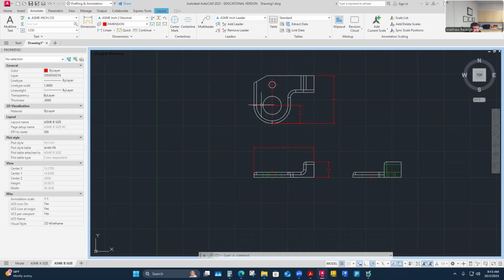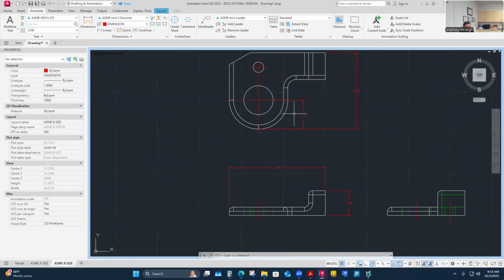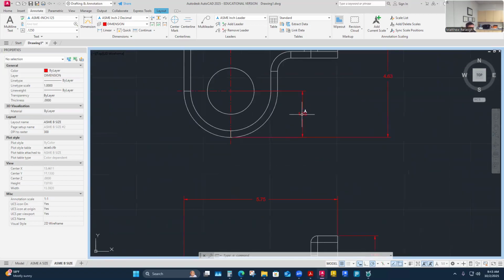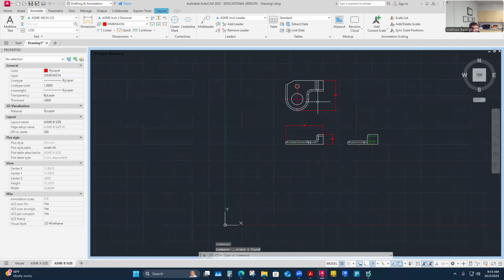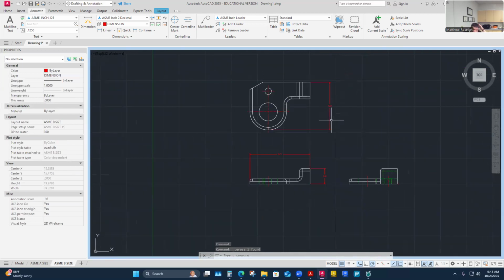Maybe you're establishing the center line of this out to here, but you've almost added a fourth pull point is what I'm talking about. And I think a good rule of thumb is try to stay as low as least amount of datums as you can to get the information across. And think about where the dimensions are, the to and from concept. So I'm going to delete that one, but I have my overalls. That's how I usually generally start.